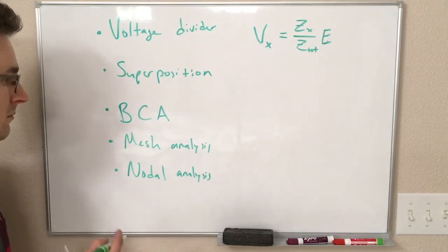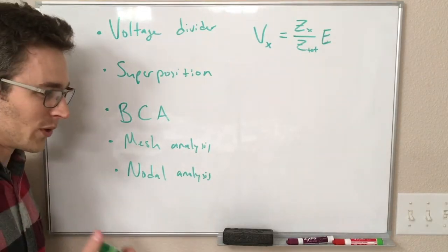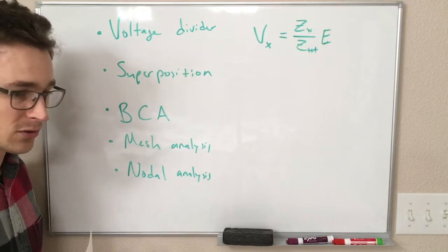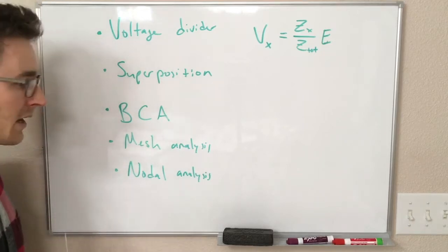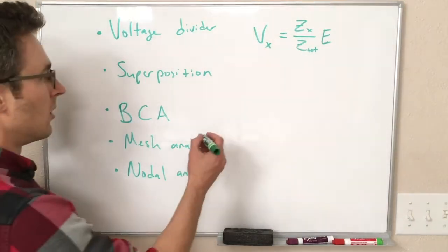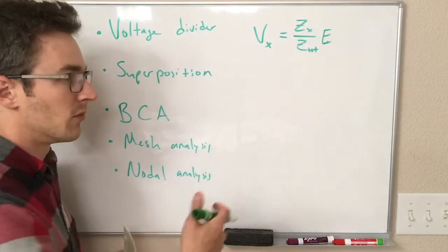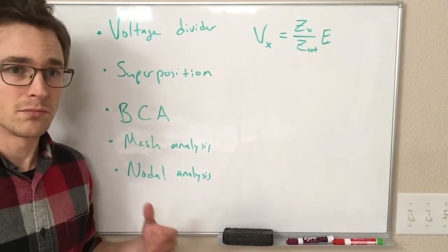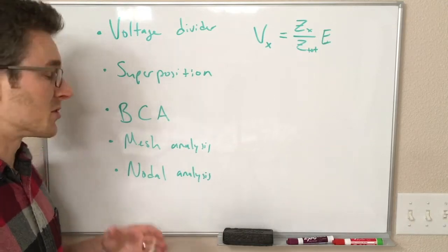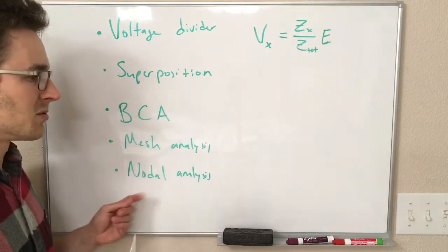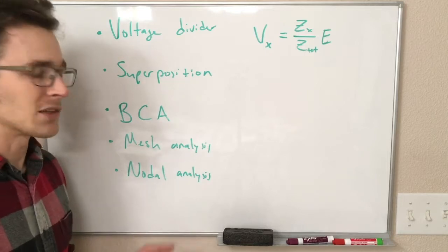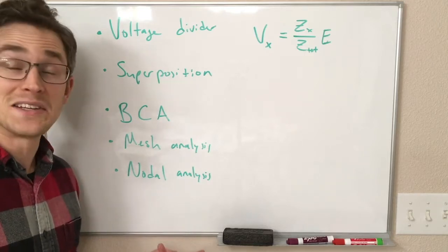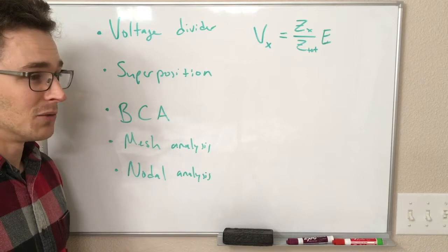We still apply Kirchhoff's laws, so we're still going to get equations that are correct, and then we just have to solve those equations. The only downside, the only thing that's harder about doing this with impedances, is, of course, that the numbers can be complex numbers. So solving the system of equations by hand can be harder. If you're doing it with a computer, it might not be any harder.